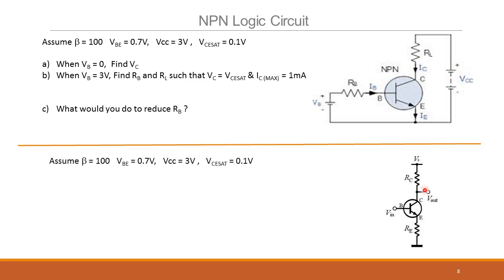You must have done this in your circuits class. Assume the same kind of transistor, right? Given that RE is 100 ohms, RC is 1 kilo ohm, find Vout in terms of Vin. What happens if Vin slightly increases, what happens to Vout? The ratio of Vout to Vin is called the gain of this configuration, not the transistor, sorry, gain of this configuration.